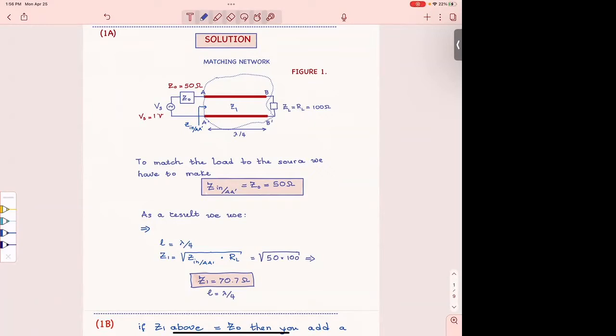100 ohm load to 50 ohm. Now, in this particular design, I do not have to give you the frequency, since you can express all of your dimensions into electrical lengths. An electrical length is a dimension in terms of a wavelength, all right? So if I don't give you a frequency, then that's where you stop. You say quarter of a wavelength.